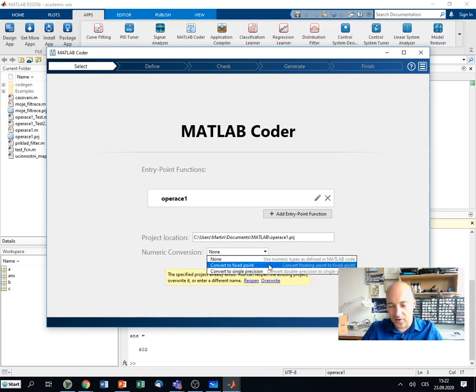So as a developer of embedded hardware, you always need to think in advance what accuracy you need, and if you really need to run everything in floats, or if you can run it in integers. On some hardware, the speed difference may be a few orders of magnitude. So if you run it in floats or in fixed point, there may be like a 1,000 times speed difference.